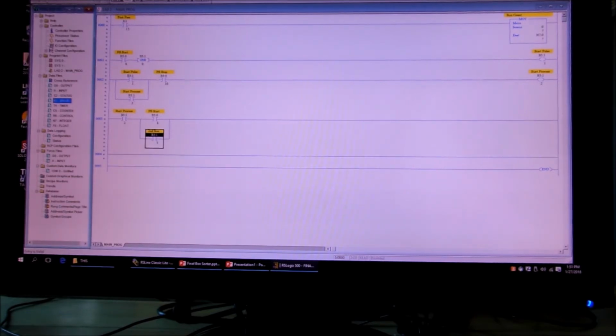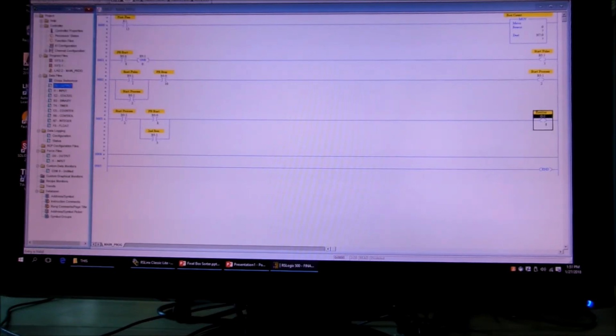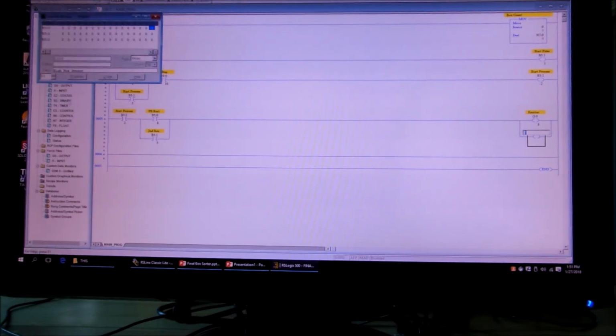That will be our emitter. I have it set up because that's one of the bits we have to move. I'm just going to make it output bit number 8. I know Peggy stresses this, but if you're going to use bits, you should just use a separate bit. This emitter bit will be our next available one.